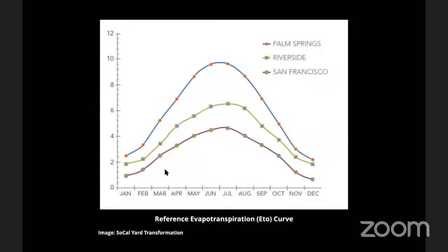And then for figuring out for your area how much water you're going to need to provide, you're going to need to understand this concept called reference evapotranspiration, which sounds very complicated. But basically, reference evapotranspiration is a way of providing a number, in inches of water, of what the highest water using plants would want in a given area and at a given time of year. So basically that's turf grass, or in agriculture, alfalfa, or also sometimes vegetables are very close. In any given area, those are the things that are going to need the absolute most water.